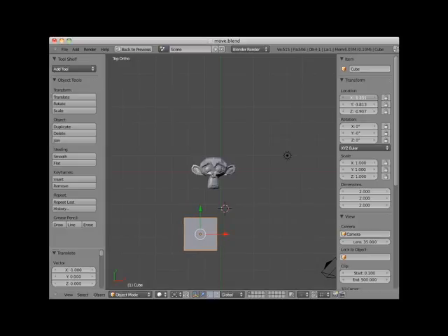I will click and drag the arrow control to the left of the Y location, and I can move the cube. I can also just type in an X, Y, or Z location. Here I will set the cube at 0x, 0y, and 0z. I'll rotate the 3D display into a user orthographic view.